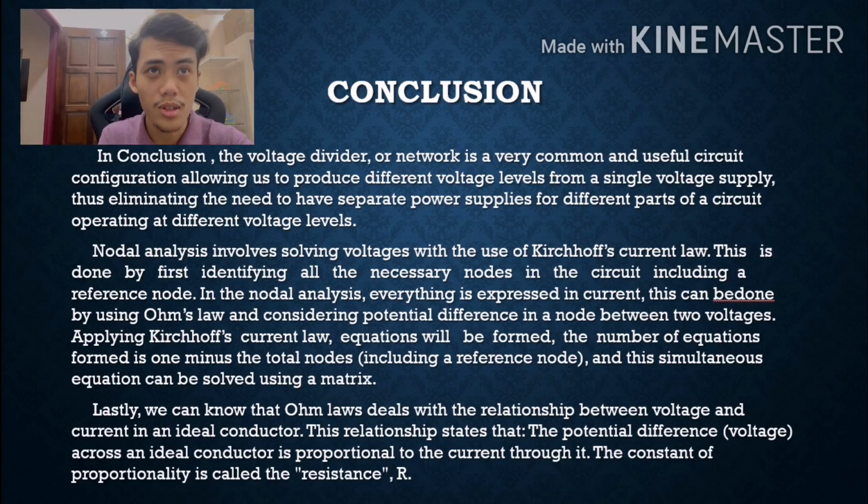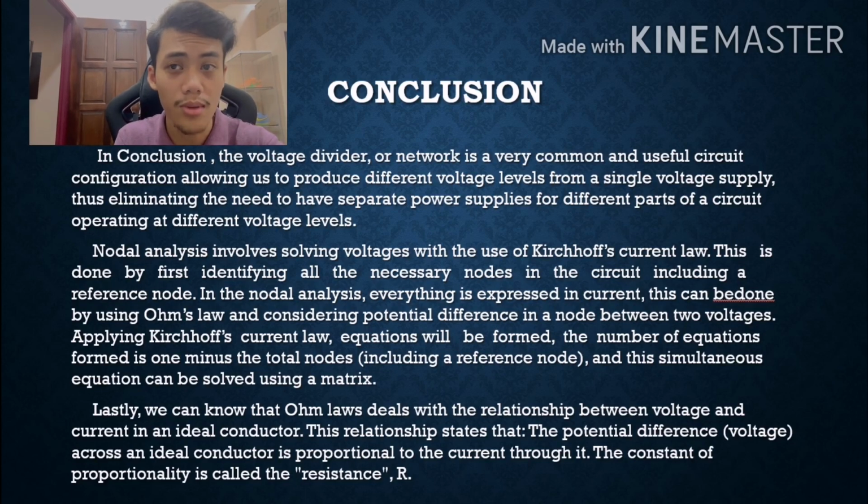Okay, in conclusion, the voltage divider network is a very common and useful circuit configuration allowing us to produce different voltage levels from a single voltage supply, thus eliminating the need to have separate power supplies for different parts of a circuit operating at different voltage levels.